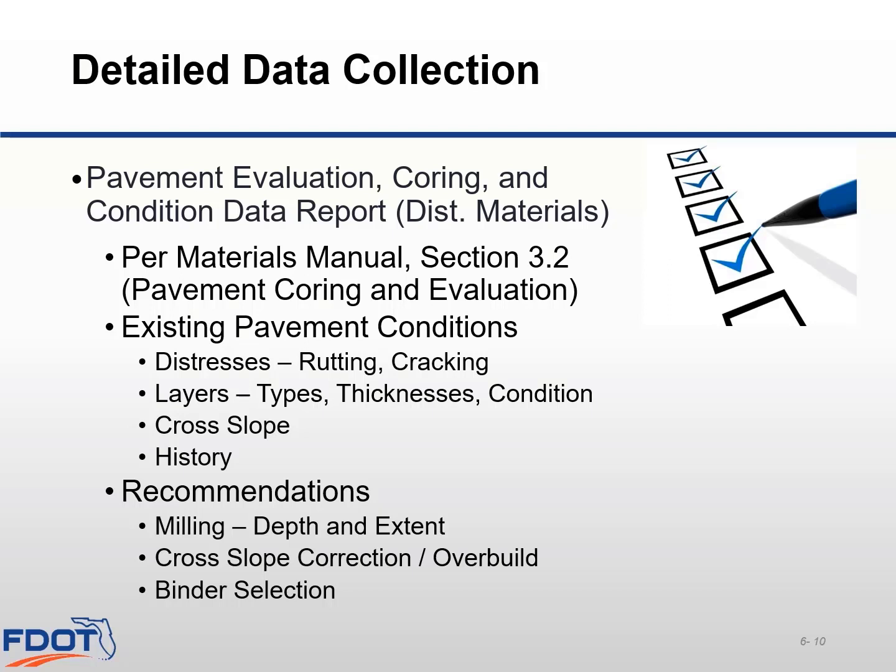The District Materials Office will also provide recommendations on milling depths and limits, any cross-slope correction and overbuild recommendations, and binder selection. Please be sure to read through the report thoroughly and discuss any remaining issues with your materials office.